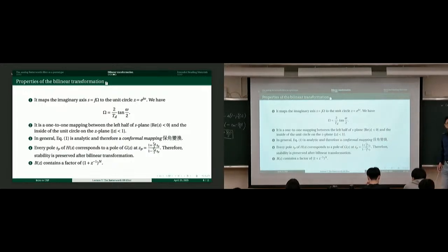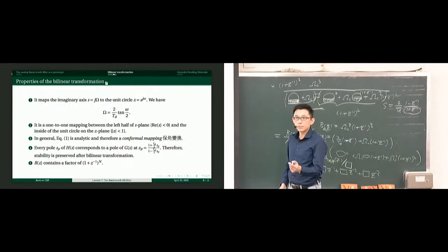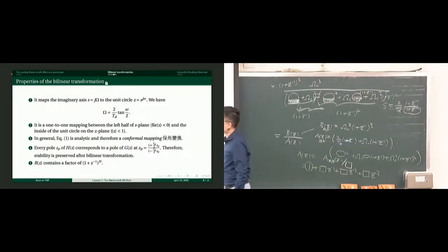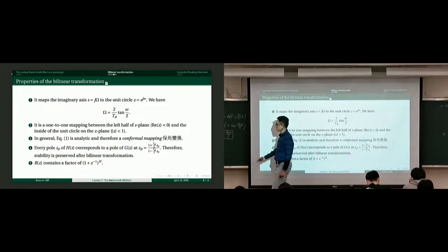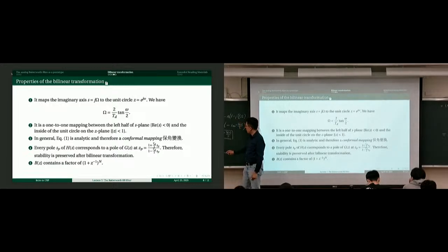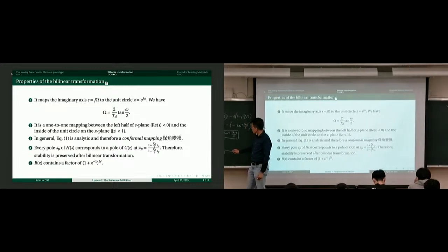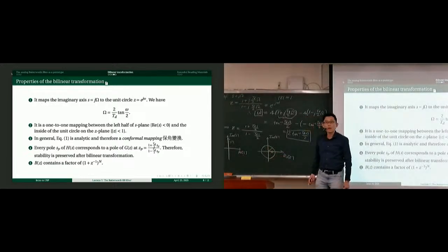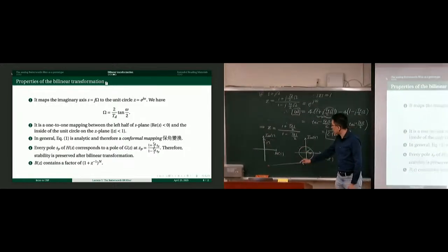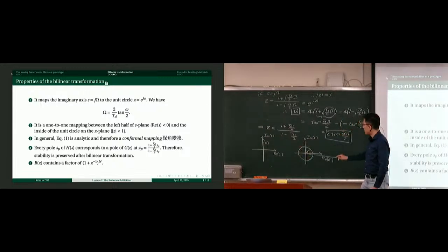So far, so good. So that's a derivation where I think our presenters last Thursday also showed the same kind of thinking process. Because of the bilinear transformation, we have checked that the imaginary axis in the s domain is mapped to the unit circle, and there's a relation between small omega and big omega. There's a one-to-one mapping between the entire imaginary axis and the unit circle.